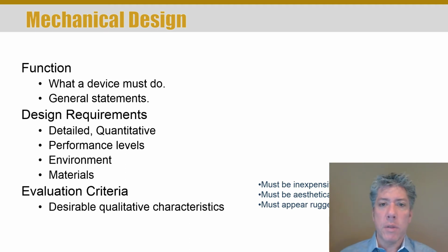It was all out of sheet metal, so it was inexpensive to make. And the spiral, basically the daisy fingers move the bolt around through the spiral so that the bolt advanced in the spiral, so that there was only one what's called pick position. So the position where the bolt would be presented was just one position, and you could program the robot to just know to go to one position over and over. It made the robot part a lot easier.